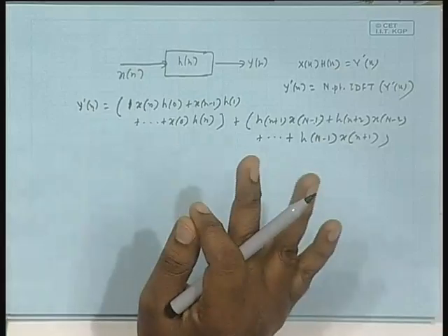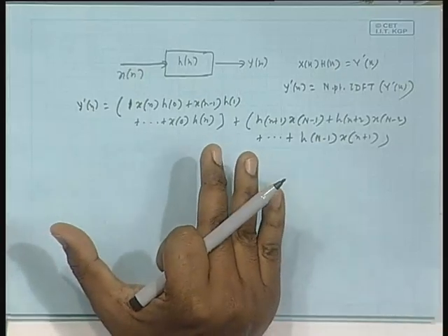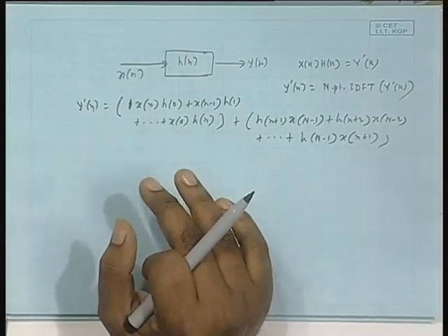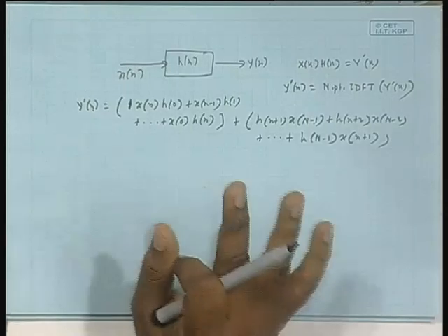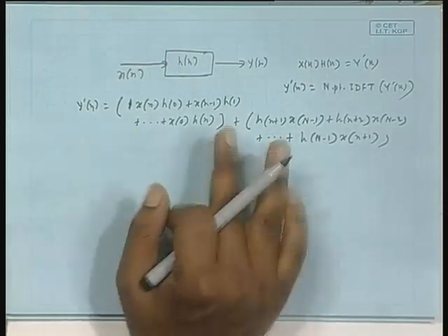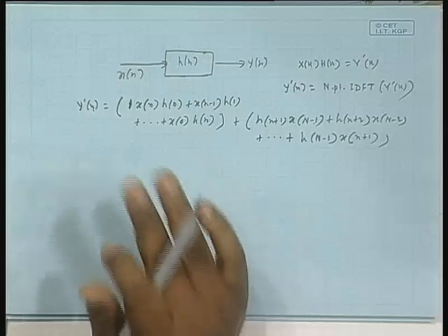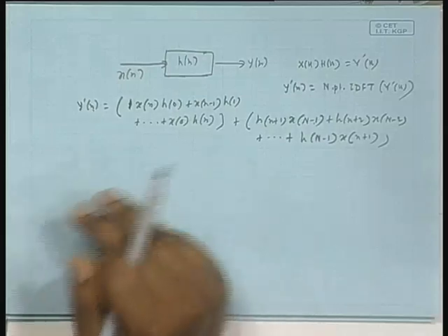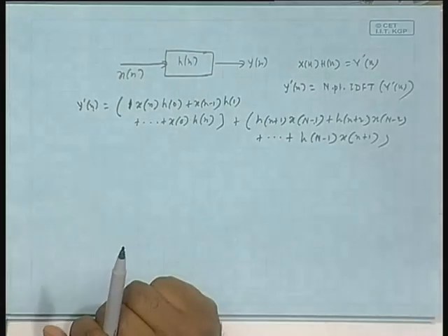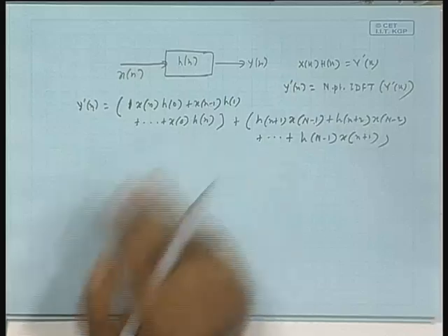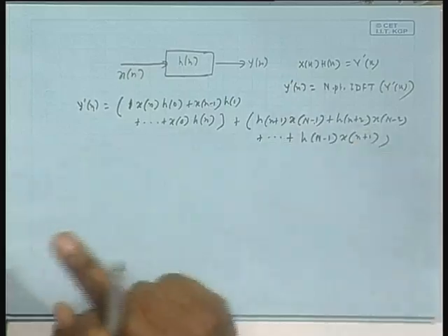So, it again becomes a finite length sequence. So, you have two finite length sequences, h n as it is and one obtained from x n in this manner, and now go on multiplying samples from top and bottom and add them, and you will get the circular convolution. That is my claim, and we will have it verified that it will indeed give you this expression.